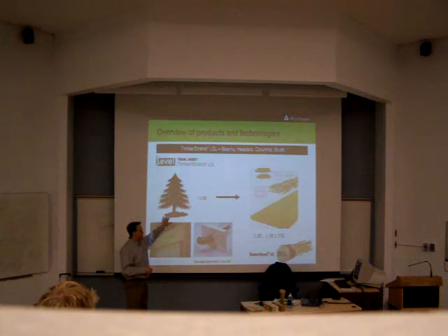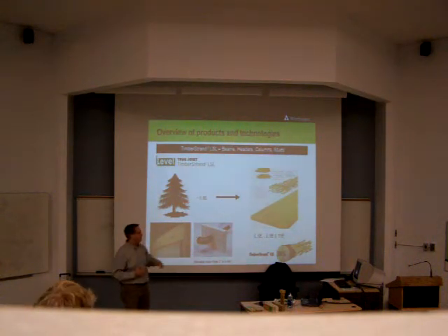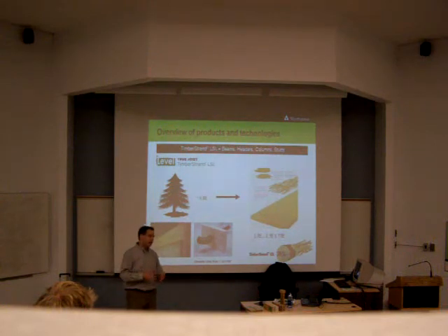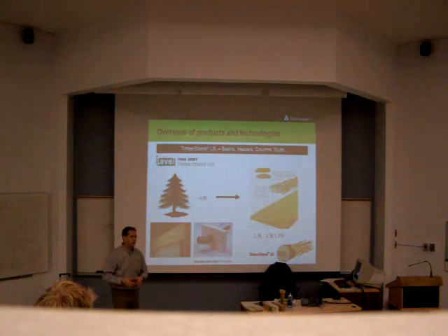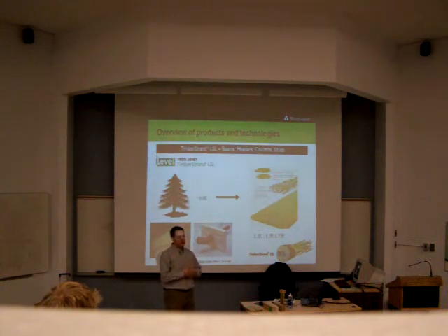Typical trees that we would use to manufacture LSL, timber strand LSL, would be aspen, poplar, trees that are very, very weak. Have a very low E-value, 0.8 E. And the average kind of spruce, pine, fir mix is normally around 1.3 E. So aspen and poplar are very weak wood species, and they never grow to be very big. They kind of grow sporadically, and after about 10-15 years, they end up falling over and dying before they actually get any bigger. It's almost like a weeded forest. So those wood species aren't really used for much, at least not in the construction industry.